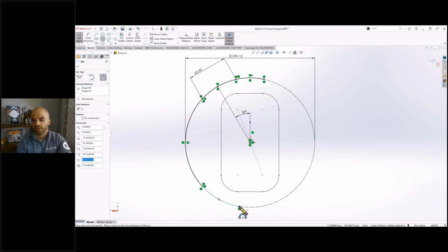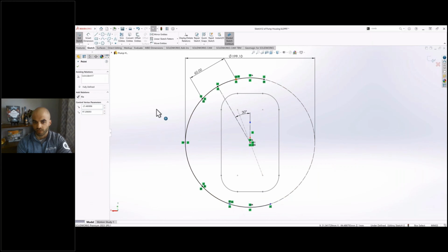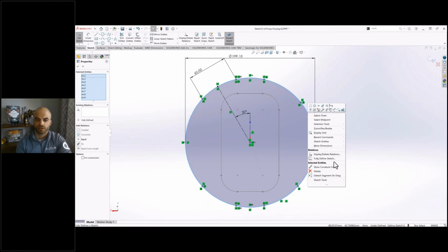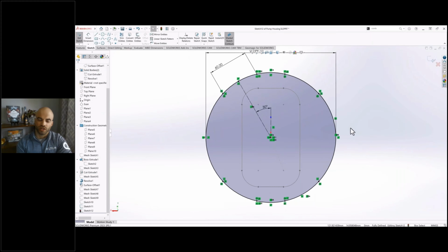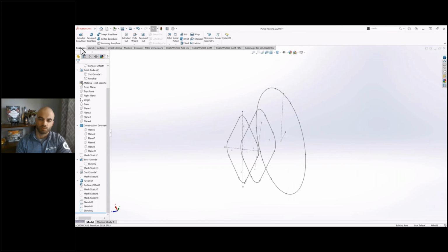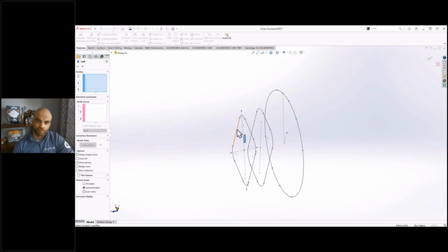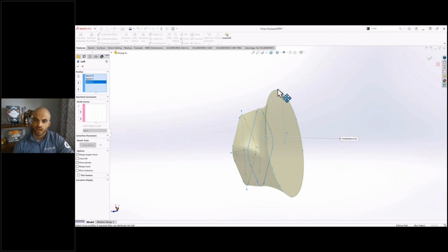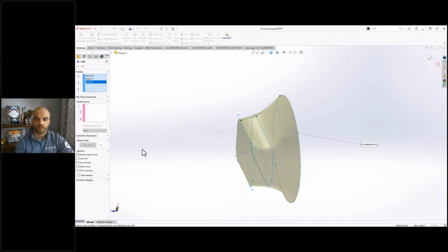Like I said, ideally they'd be lines and arcs, but obviously that's not the same profile at all, and it would give us bad data. So we're doing it all with arcs, but I'm trying to generally line them up. That's what that first 30 degrees and 60 millimeters was. I'm just trying to line up that corner area so that the points flow along the loft properly. So I split that single circle into 8 arcs, so that it behaves a little nicer with the loft. Leaving it as a circle would probably work fine, but lofting can be complex enough as it is, and giving the system exactly what it's expecting, served up on a silver platter, generally leads to fewer headaches down the line.